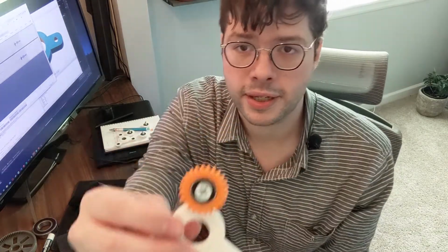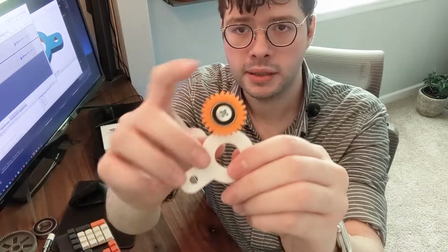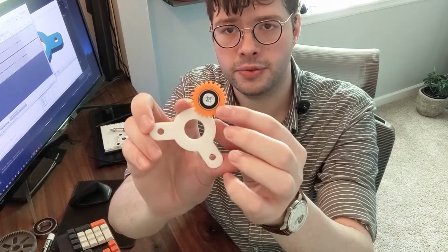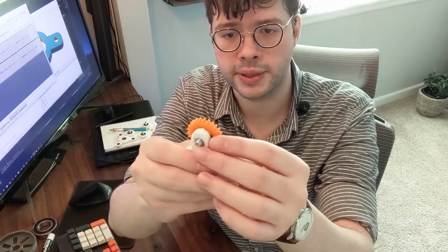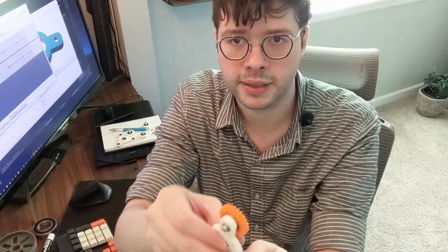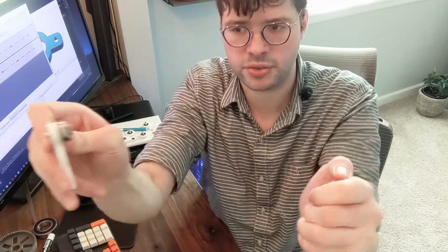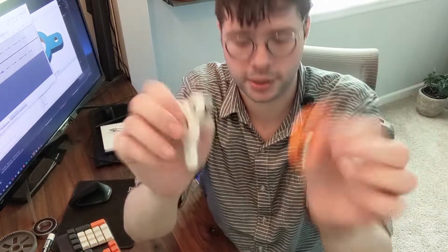And that is pretty much all I did for making sure that everything could rotate. Now let's talk about design consideration number 3. Although we have this gear and it can rotate freely and it is attached to the arm, it has one somewhat major design flaw. Because it is using a pressure fit mechanism to hold the bearing in place and my tolerances aren't that great, the worst part is if I just pull with not even really that much force, I can bring the whole thing apart, and that's kind of weird.